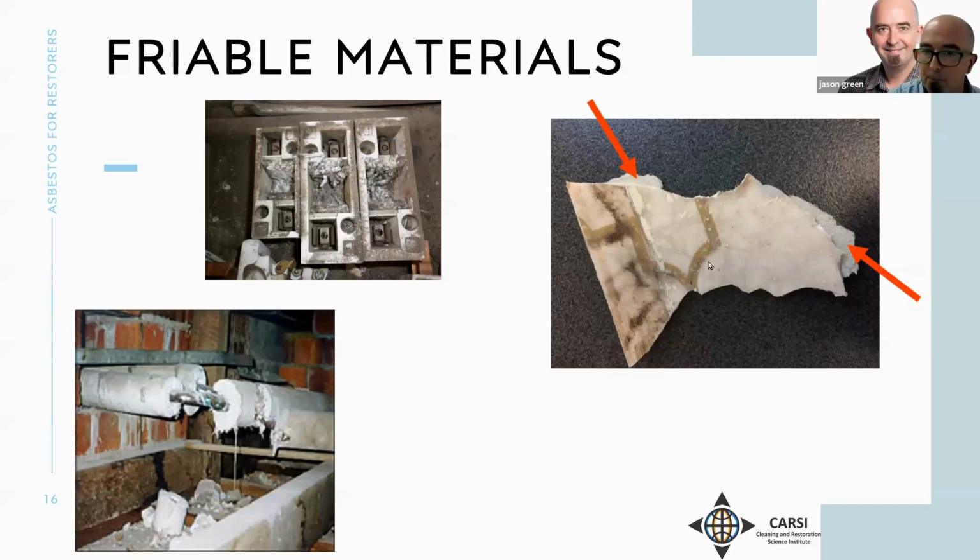Very concerning, as that material has a very high percentage of asbestos, and this sheeting is generally stuck down with glue. The glue may contain asbestos, and when you try to pull this up, it makes a massive mess, with a high probability of getting exposed in a major way if that material is being removed without knowing.